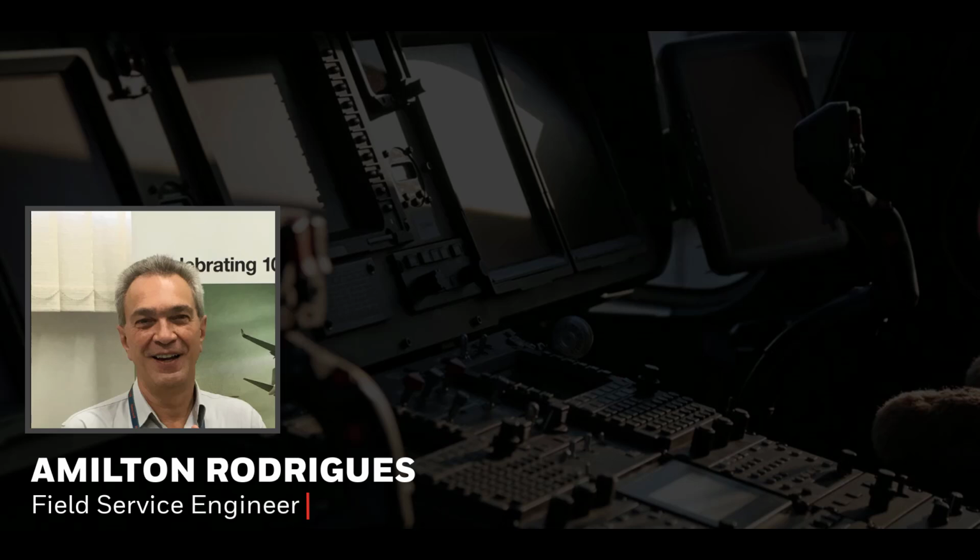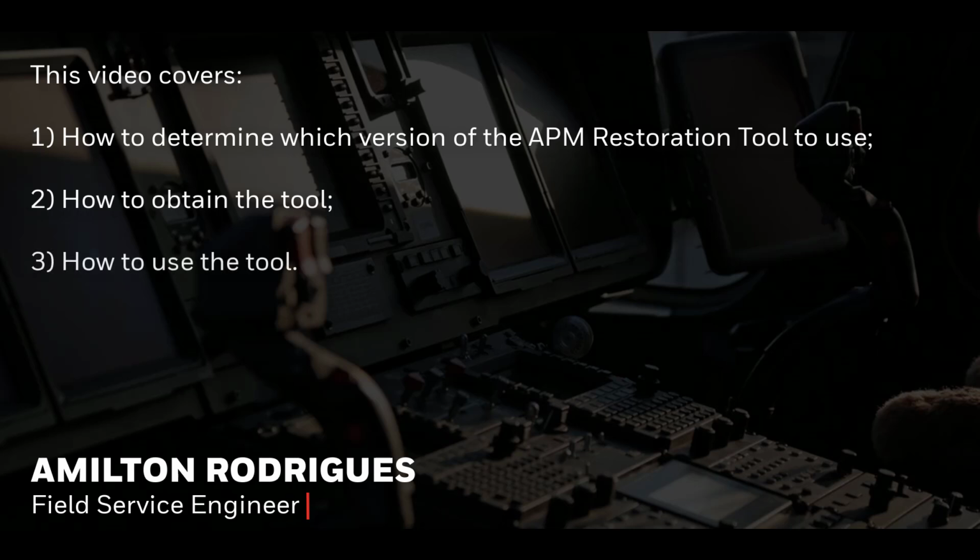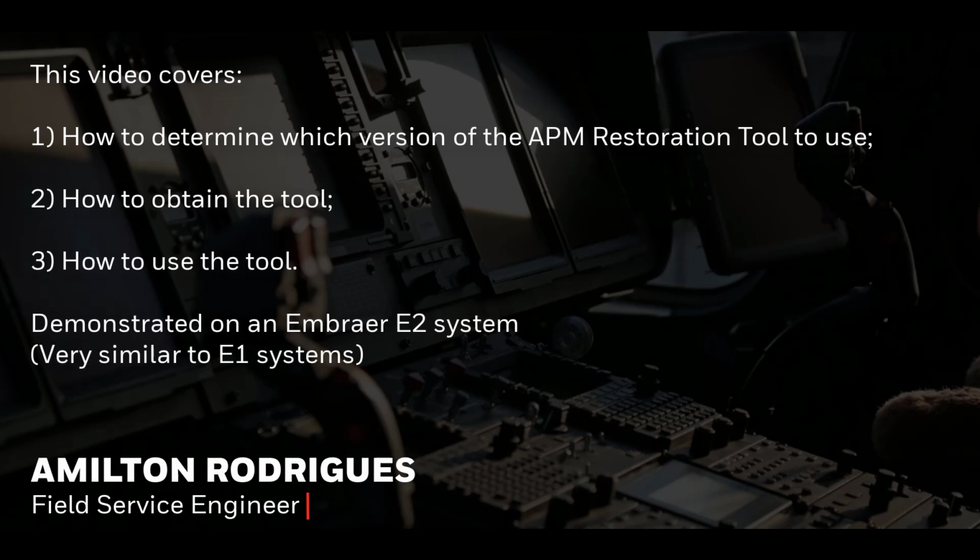The purpose of this video is to demonstrate the APM Restoration tool, covering identification of the correct version, how to obtain it, and also its operation. This tool is normally used to troubleshoot an APM miscompare cache message and also to restore system operation when an APM hardware or MRC cabinet is replaced. The demonstration will be on an Embraer E2 system, but its operation is very similar on E1 systems.